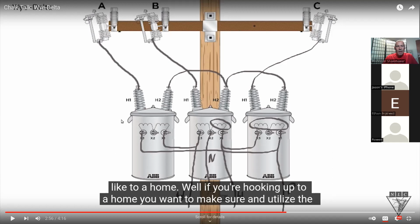Usually we carry it behind, go all the way around the back of the pole and come up, tying the X3 and X1 bushings together, then come down with one wire. Electrically, it still works. One's a schematic drawing. One's a drawing that you're going to see out there in the real world. This is more real world of what you're going to be looking at.